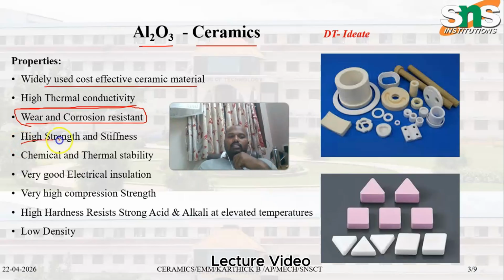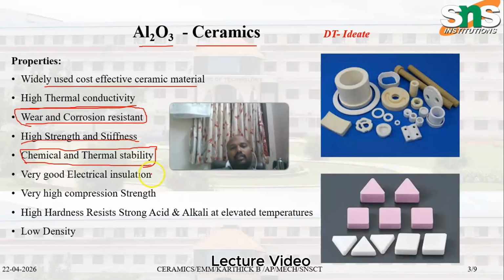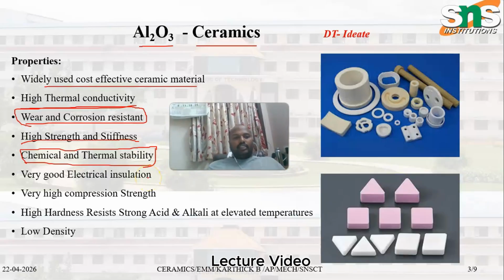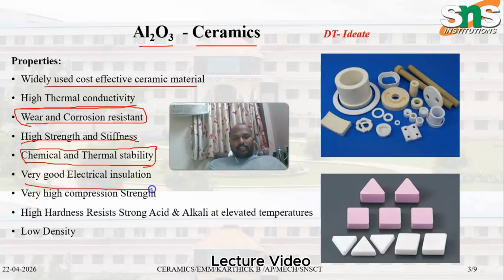High strength and stiffness come into play when it is used for abrasives. Chemical and thermal stability is why Al2O3 ceramic is used as the spark plug, where thermal and chemical stability are very important in order to withstand the heat. It is also a very good electrical insulator. Because of this property, it is used in spark plugs, and it has very high compression strength.